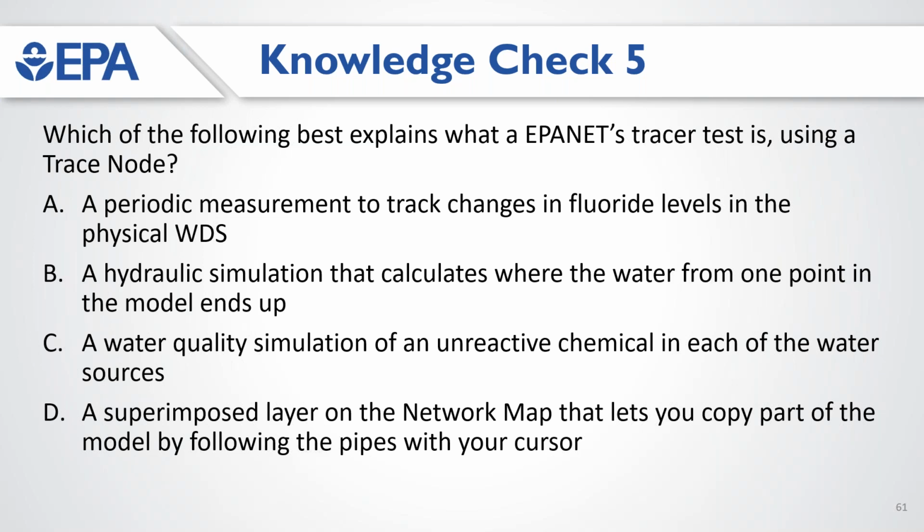Well, I think I need to do some reflection about next year's presentation, because tracer analysis, the tracer test in EPANET, is a water quality simulation. It's not a hydraulic simulation. But I think the question, maybe the wording has some problem, so we need to work hard on the wording of the question, I guess. But a tracer test is basically a water quality analysis.